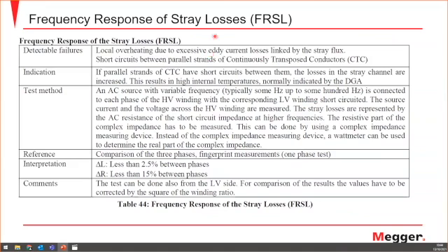I have very good explanation slides, which I will go through in the next slides, showing what exactly this is and why it shows eddy current losses. Also, if you have stray flux, the results of this test will tell you that too, what it should be, what it should look like, and what is even the acceptable percentage from the delta of inductance or delta of resistance. We will focus more on the resistance. Delta resistance: it's strange, as resistance should always be the same at any frequency, but let's see what is happening.